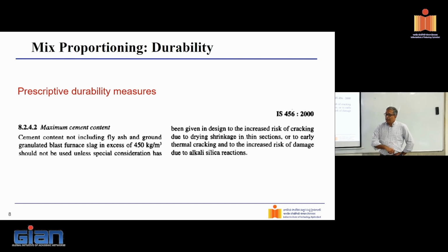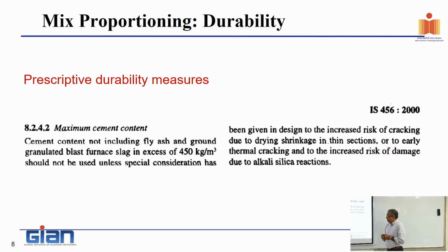Or if my water to cement ratio decreases, the paste becomes thicker, more viscous, and has more yield stress. Of course, these are all consequences that we have to live with. But more importantly, if you start increasing your cement content, the paste would shrink more. It would produce a lot more heat. These would then produce unintended consequences of cracking because of shrinkage and thermal effects, right?